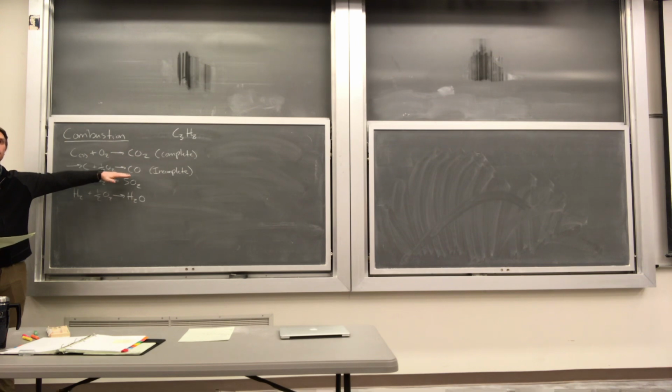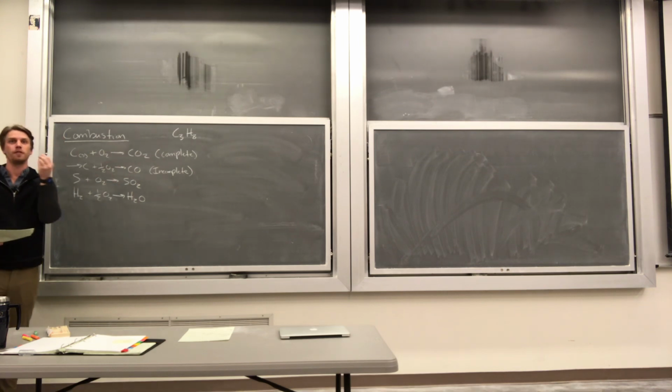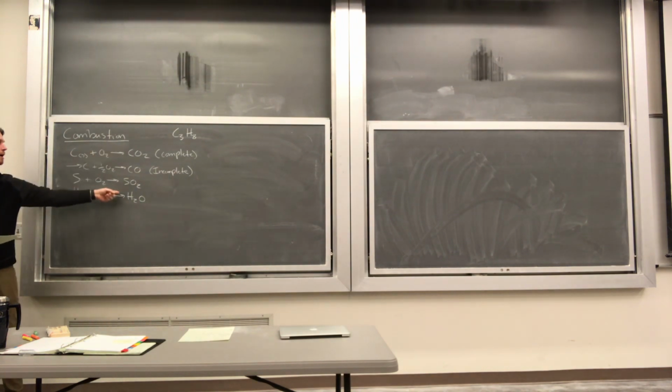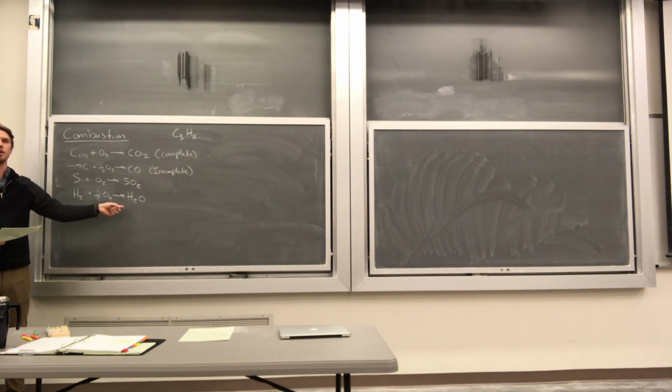But in the real world, you may have incomplete combustion, right? Because these large industrial burners are huge. So there is still active research into how to design the injection ports, the shapes of the nozzles, what shape of flame do you want. That all helps us determine how we can reduce the amount of sulfur dioxides, or for example, NOx material.